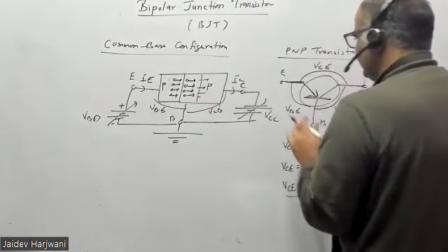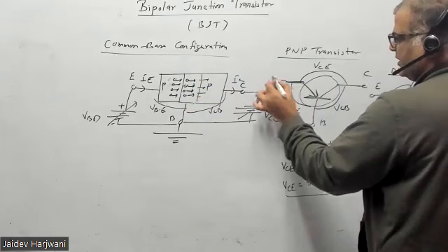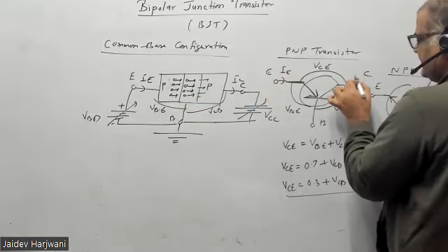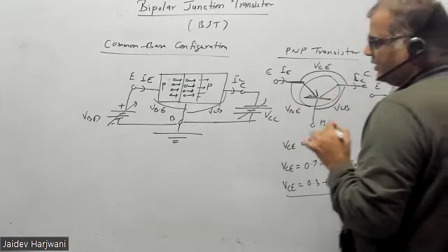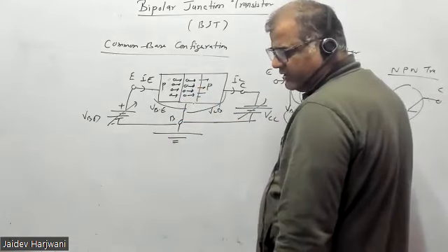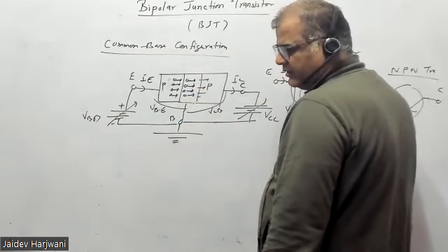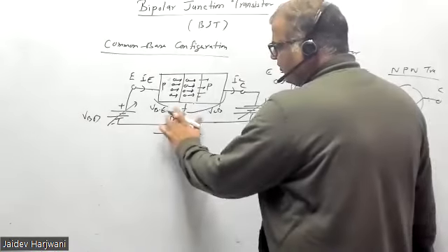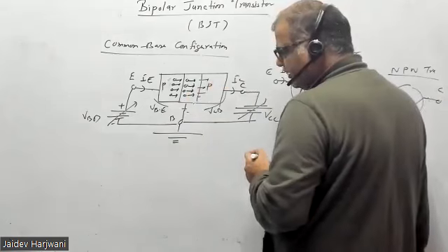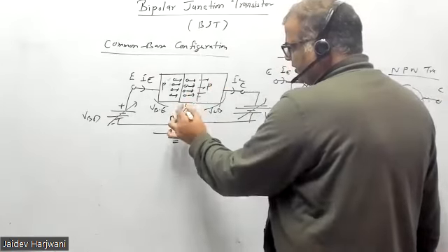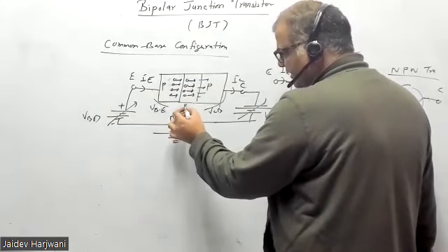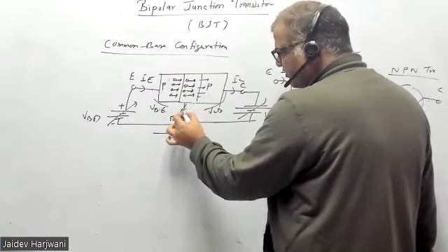Basically, what is happening when you apply an ammeter is that a current I is flowing here, and IC is going down. Now, because some of the holes get recombined here, holes are reducing, which means they have to come from somewhere. These holes are reducing, that means electrons are increasing. So these holes will come from this terminal.